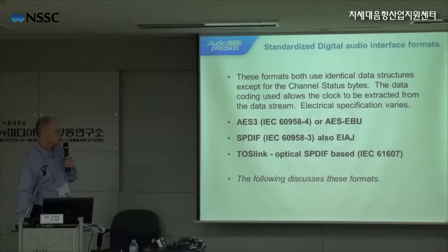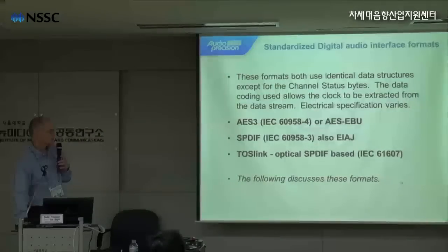So the interfaces are AES-3, sometimes called AES-EBU, and that's according to standard IEC 60958-4. There's SPDIF, that's IEC 60958-3, and the Toslink optical, SPDIF based, IEC 61607. So we're going to talk about the common elements of these three formats.